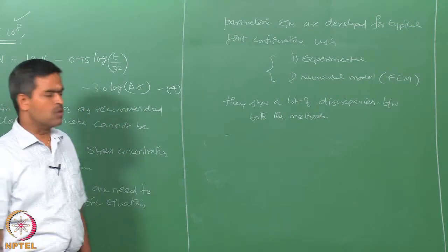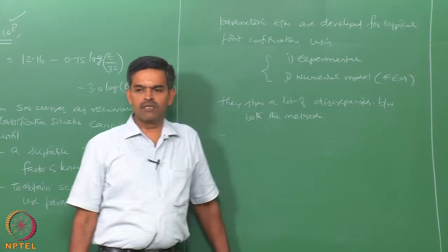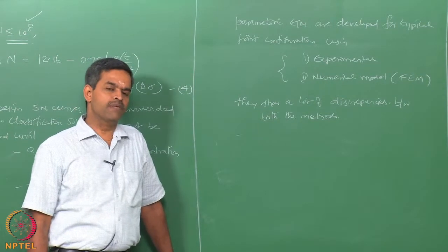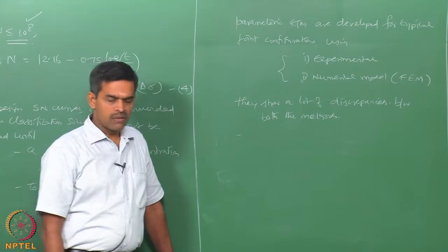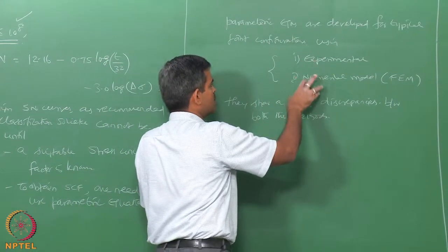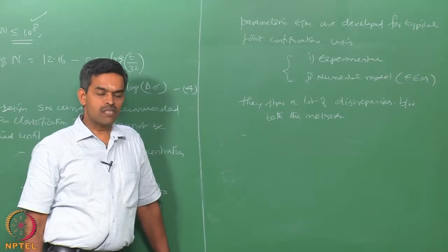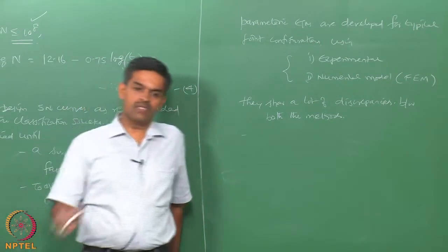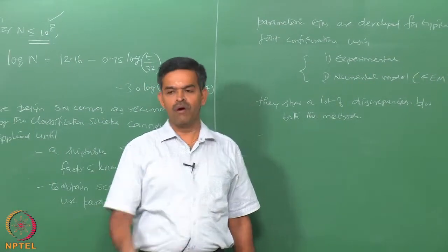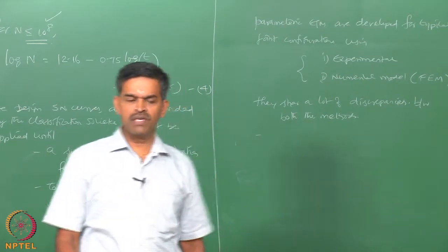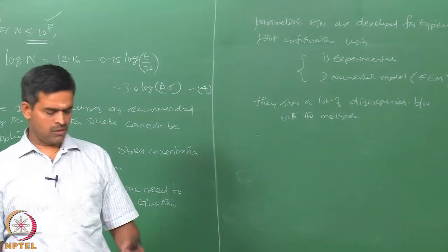One is interested to know the probability of failure when the system is subject to cyclic loads, what we call fatigue assessment or fatigue failure. Even in assessing fatigue failure there are inbuilt uncertainties even at the design stage, which the design SN curve is supposed to account for, an improved form of a conventional conservative SN approach suggested by various researchers.